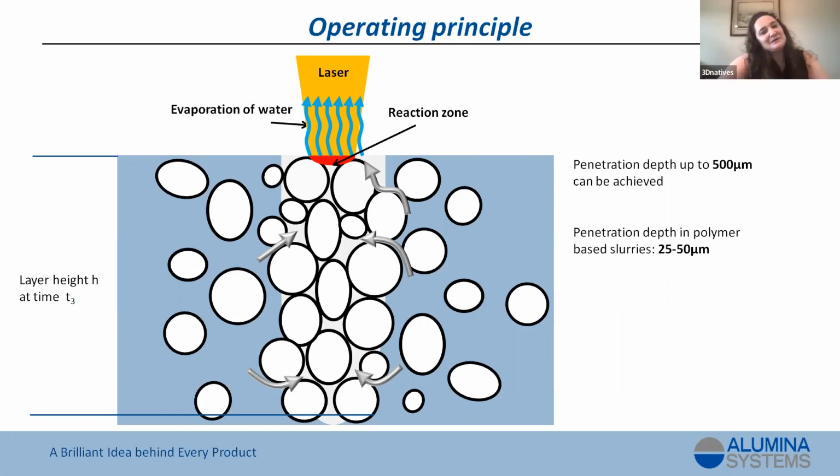And then just a couple more. What would you say is the max thickness for alumina and dark ceramics, in terms of wall thickness? Holger, what did you already achieve? For alumina we are at more than 20 millimeters, and for silicon carbide we have no expertise right now.